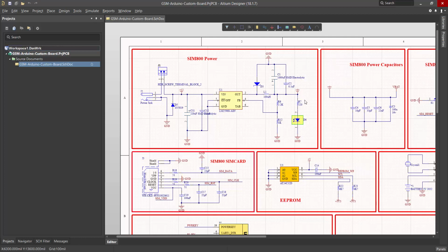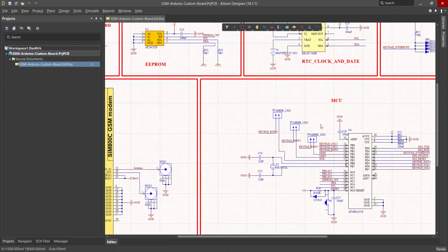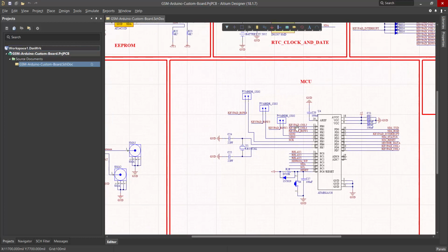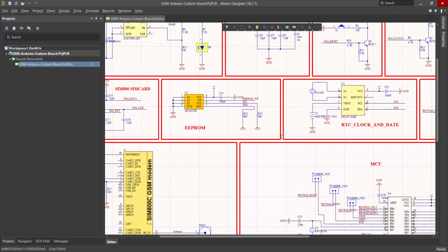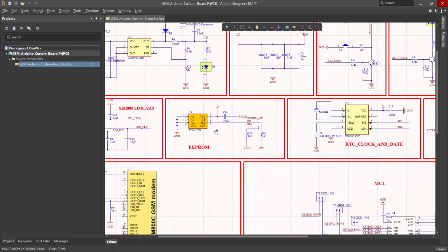Therefore, it can produce some high frequency noise on our power rails that is very harmful to sensitive parts of our board, like MCU, and cause reset in our MCU or wrong operation in our sensitive digital sections, and our board will not work properly.